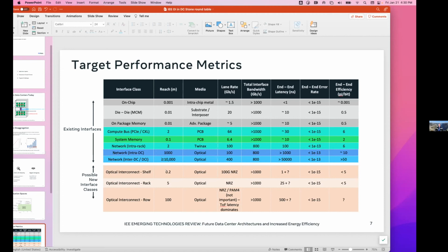Absolutely. Fair. And I think the other thing, it's probably been said somewhere, is you're looking at chiplets, right? So if you're going to do this, I don't know if co-packaged optics is the right term, but if you're going to do this integration where you're die stacking your photonics IC on the same ASIC, for lack of a better term, you're not going to end up using one of these SerDes interfaces anyway. You're going to use some tiny, low fraction-of-a-picojoule-per-bit die-to-die interconnect type interface at massive bandwidth.